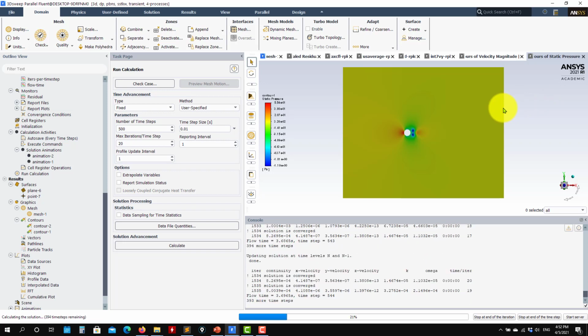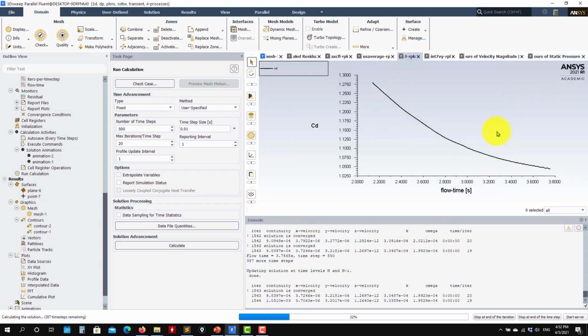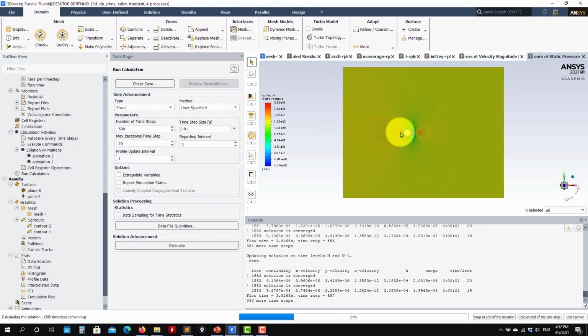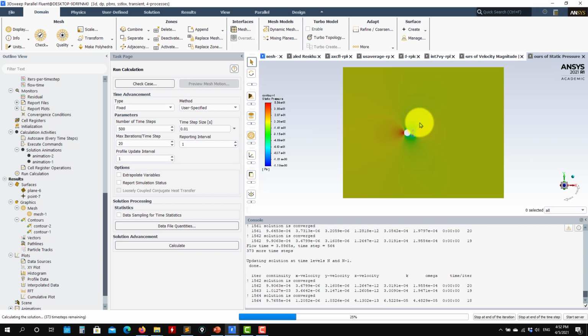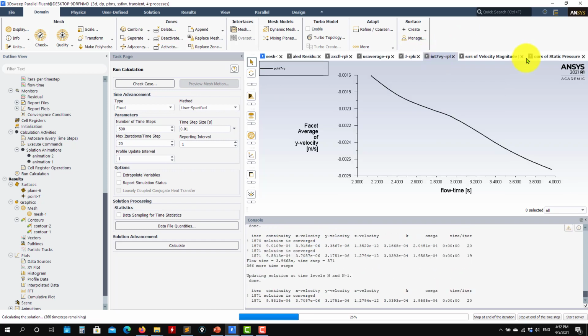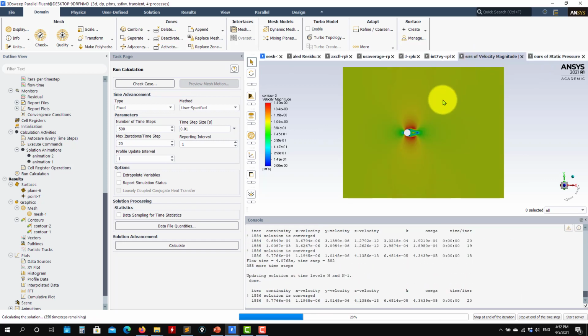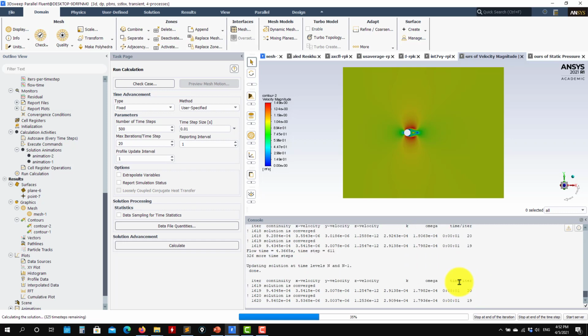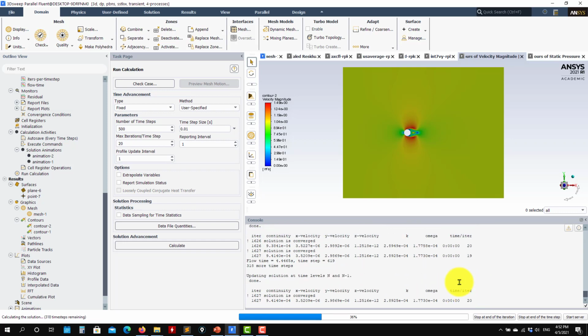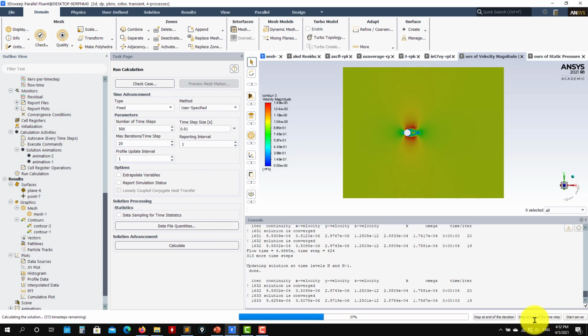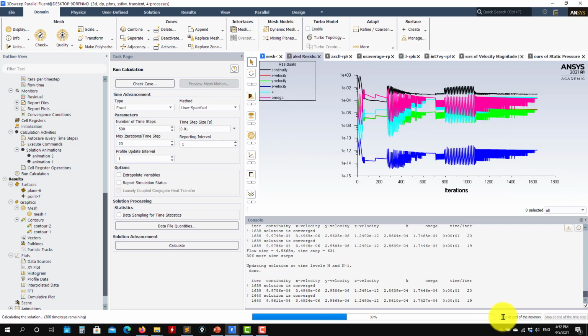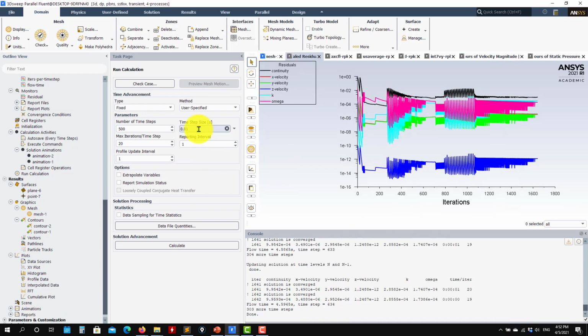And see that it's not only looking at these quantities, it's also important to look at the color, because the colors also give you some information that is not contained in those quantities. So see that you have all the evolution here, and it is converging in one iteration. When you see this converging in one iteration, or basically in 1, this is also an indication that you can still increase your CFL number.